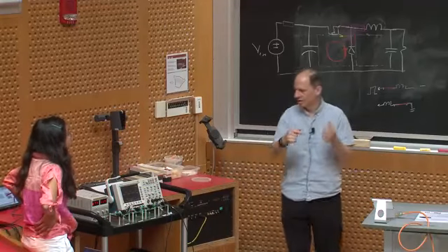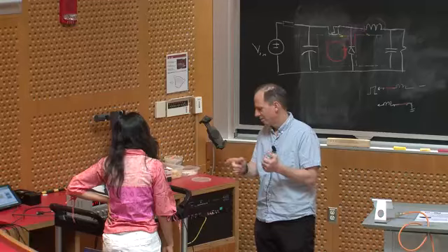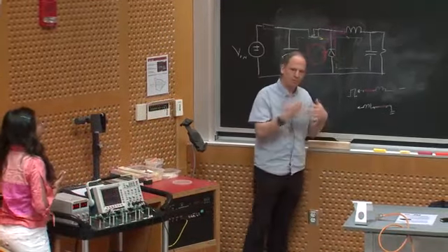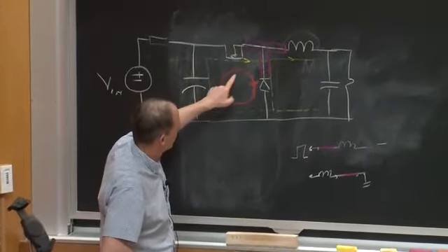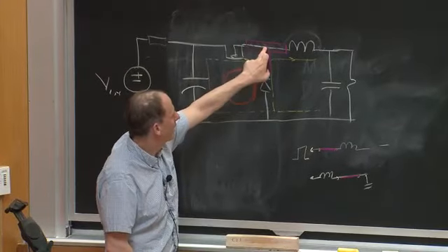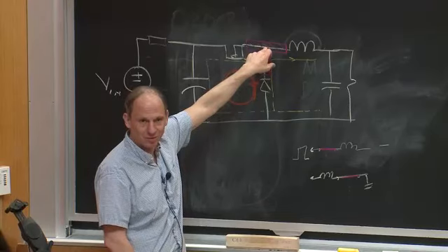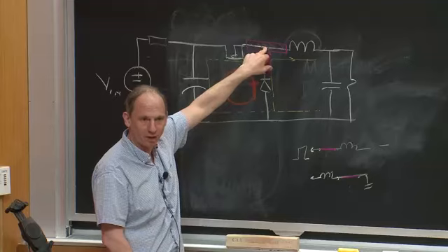Okay, since I have the mic, which case are you going to do first? We can start with the worst case one. So we have a big switch gap and a big switch. Yeah. So suppose I did a bad thing in two dimensions. I made this loop terrible, and I have excess area on this switching node. So I'm just doing a bad job of laying out my circuit. What would that waveform look like?